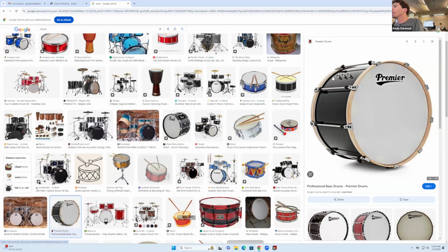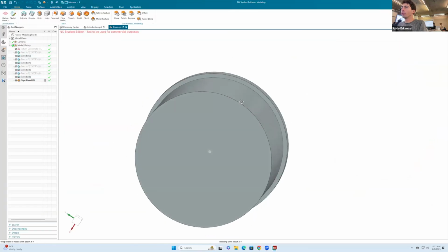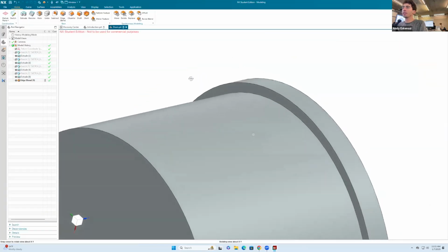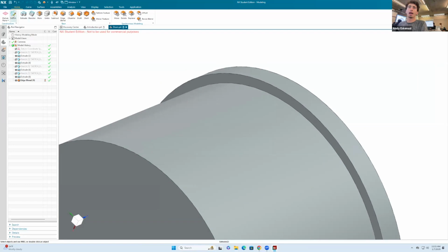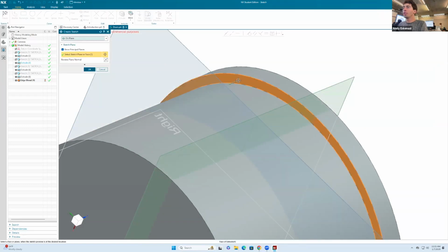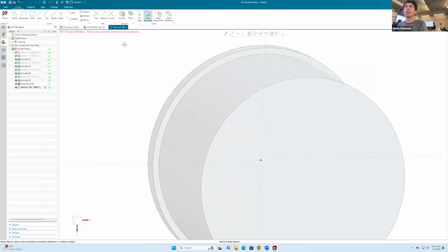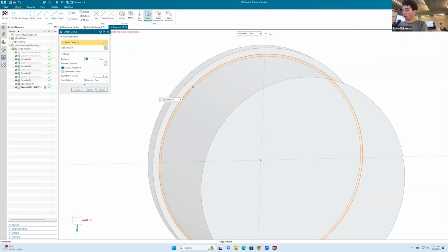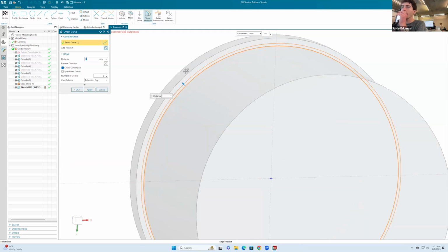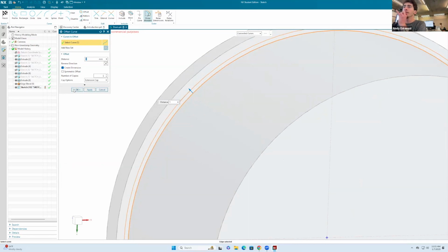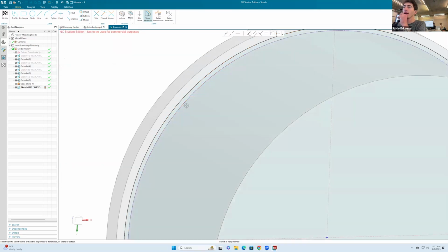You see, there's also a little gap in there, and there's also that little metal piece. So let's add that as well, right? So I'm gonna go to this side in here. I'll do a sketch on this face. I'll say okay. And now we'll go to offset. Let's offset by maybe 1 millimeter in that direction. I'll say okay.